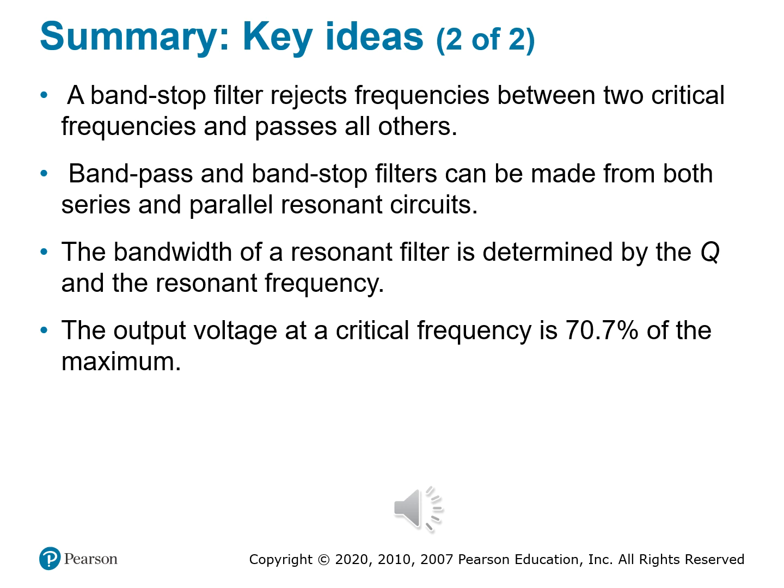So filter wisdom in 4 lines, 1, 2, 3, 4 bullets. We got band stop filters, the rejection specialists. These circuits block a narrow band of frequencies and pass everything else. You can picture them as sound engineers muting that annoying 60 hertz hum while letting your music flow. Then the next one is versatility in construction. When you're dealing with both bandpass and bandstop filters, they can be built from series or parallel resonance circuits. And the trick in the topology is what frequencies you're aiming to filter.